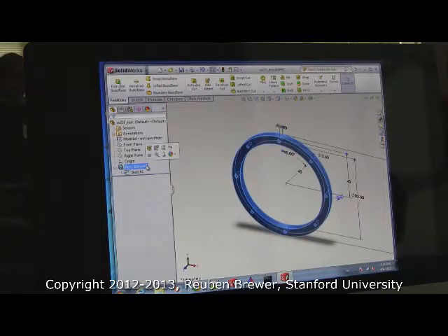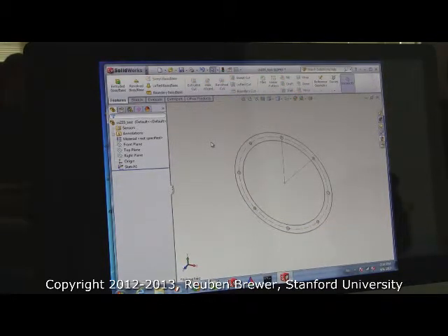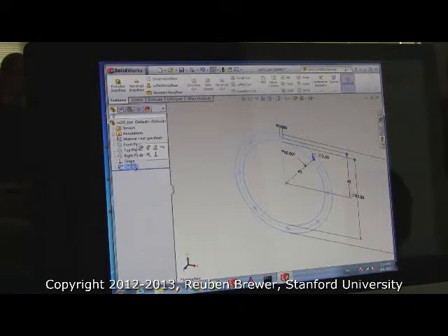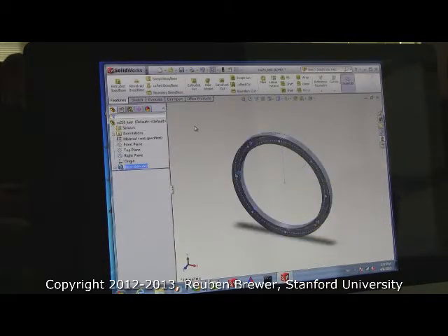Sometimes you get to the point where, for some reason, you only have a sketch. So go ahead and select boss and hit delete and hit yes. And we're left with just a sketch. Okay? Sometimes what will happen is you'll make the sketch and you'll have a slight error and you'll fix the error, but then it'll kick you out of the feature menu. So you fix your sketch and the sketch is good, but now you're like, oh, what happened? I'm not extruding. Just select your sketch and hit the extrude button again, and we're back where we were. So you can either make an extrude starting from scratch by clicking on a plane and sketching, or from another sketch you've already made and you just select the sketch and hit extrude.